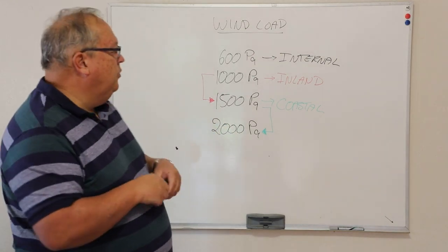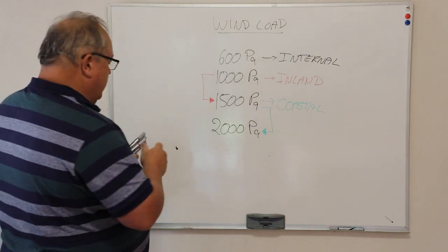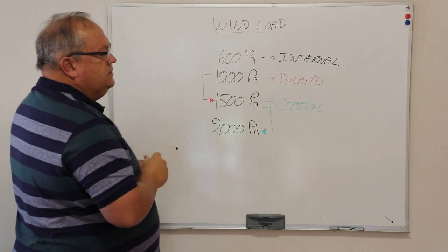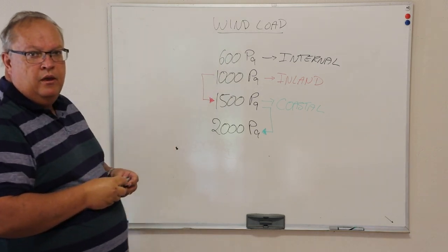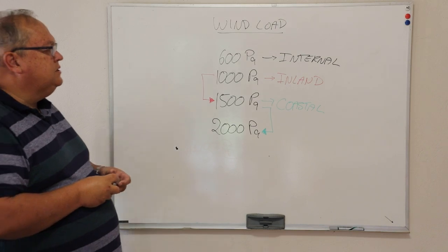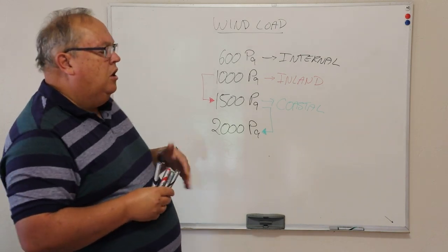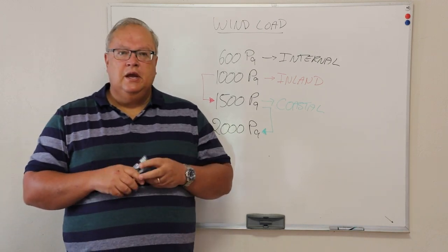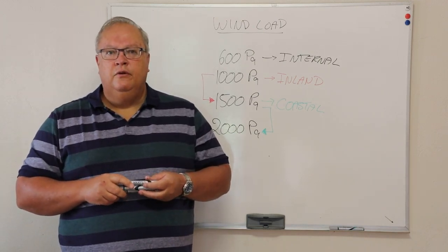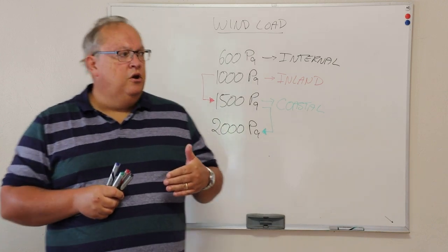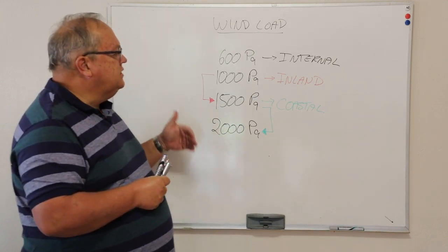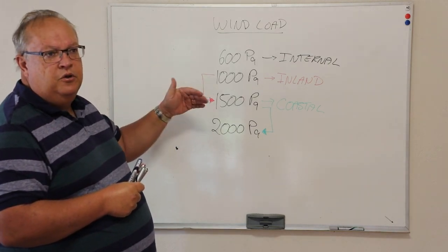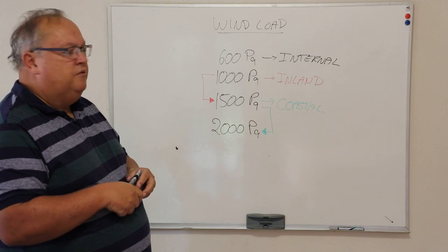Now, every single design that you do on StarFront requires you to specify the wind load, because that wind load is an important factor for determining the amounts that that profile will bend when it is exposed to that wind. You cannot simply just work on wind speed. If an architect says to you, the average wind speed in that area is 15 meters per second, that's not enough. You have to have the wind load, because the wind load takes into consideration the temperature, the pressure, the humidity, and the wind speed of that parcel event.